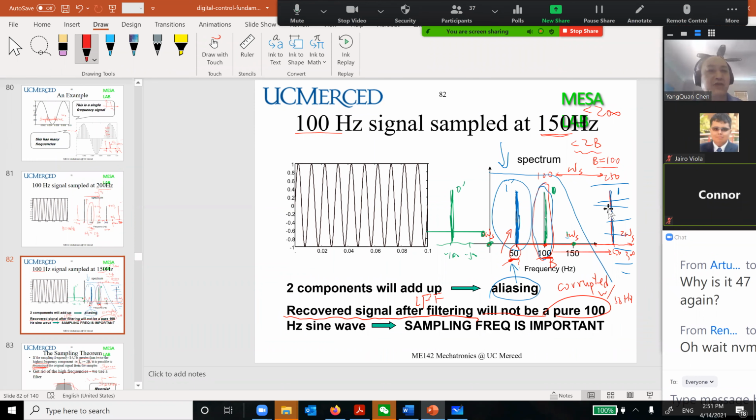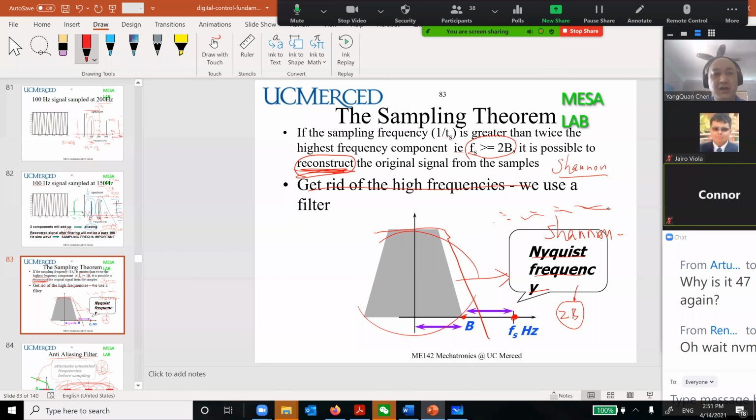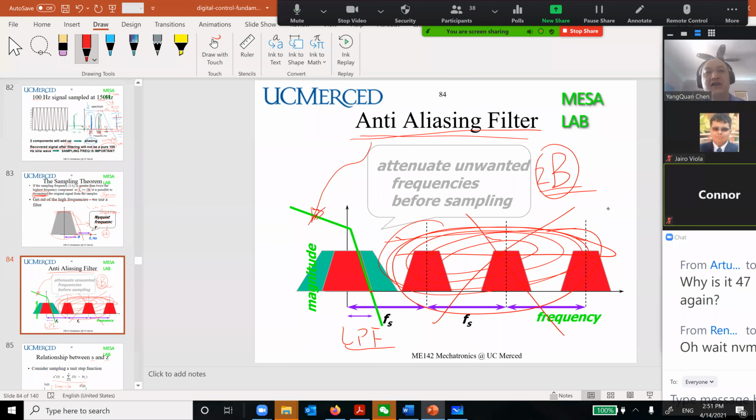Okay, if you add a low pass filter, you can cancel out all the higher frequencies, but you still have this 100 left. You keep 100, you'll keep 50. So the aliasing is very bad. If you have an alias, the signal is very bad. It will make your life much more miserable. Okay, so anti-aliasing and aliasing is important. So usually in our hardware, we already give you this anti-aliasing filter there already. So you should not worry about high frequencies being reflected into low frequency. So don't worry about that.